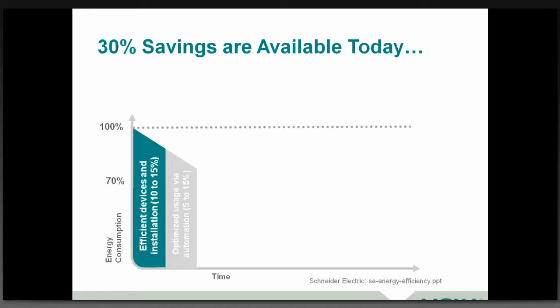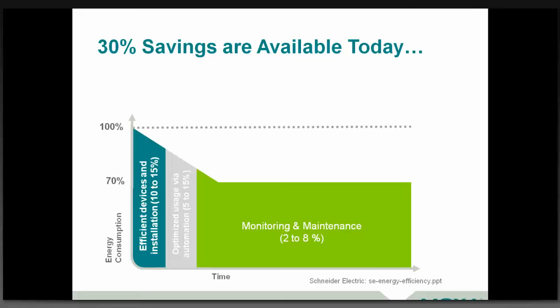In other scenarios, and we'll talk a little bit more about this, some of you may be charged by peak demand. Optimization can come through optimization to reduce your energy demand and shave those peak demands. This might mean different scenarios where you do not turn on certain pieces of equipment at that peak time and schedule those a little bit, or balance your usage to not hit those peak demand charges and have to pay higher rates for your electricity usage, right? So that's through the automation end of it.